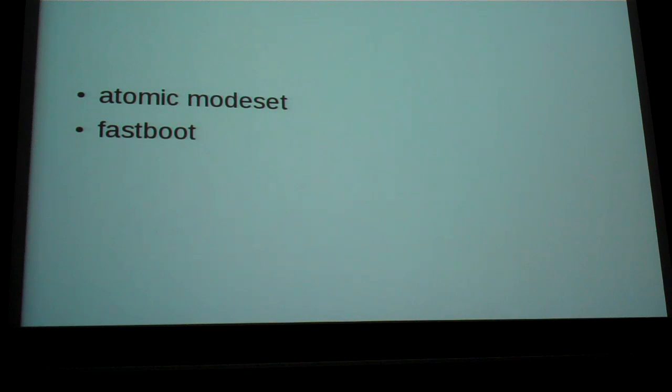So looking ahead for mode set stuff, there's a bit less atomic stuff on the table, certainly, and especially for some of the resource sharing issues, I think having our own mode set infrastructure will help greatly, so that we can pass around special properties and implement resource constraints. For example, on Ivy Bridge we have 3 output pipes, but in a lot of the resources we actually only have like 2. So if you want to use more than 2 PCH ports, you need to share the PLLs. There are link bandwidth constraints on pipe B and C. So if you use both of them, the link bandwidth cannot go above certain limits, whereas if you just use one of them, it can.